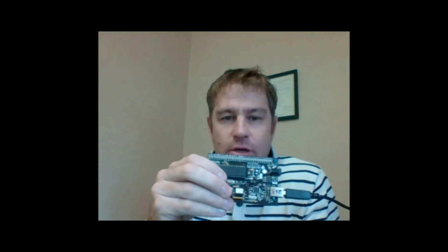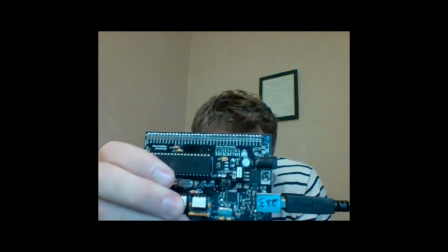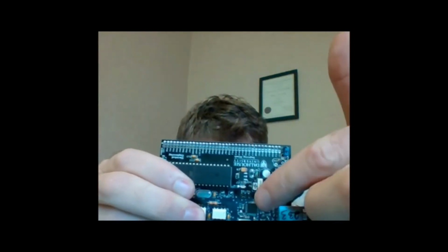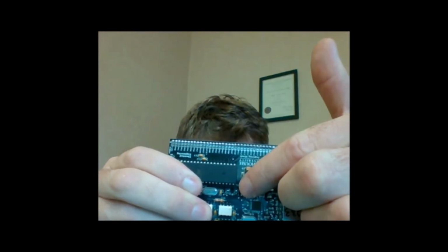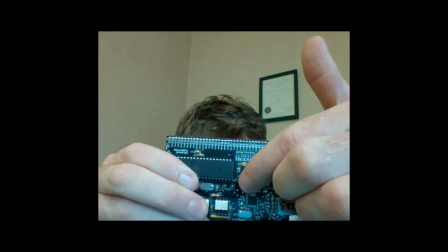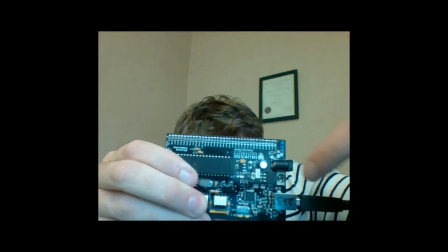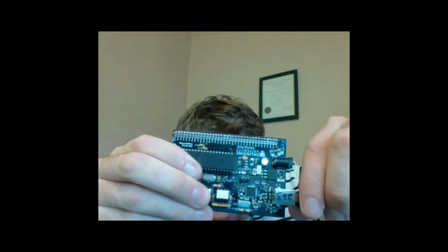And in fact, to actually communicate to the chip, you have to make sure that there's two jumpers that are labeled as TXD and RXD. The jumpers have to be soldered. I don't think that this will be, perhaps this will be visible over here. Actually, I think it is visible. So you can see it here. You have two jumpers, and I've actually soldered two beads on top of the solder so that we have a connection between the two interfaces. I think those are the important features of the board.